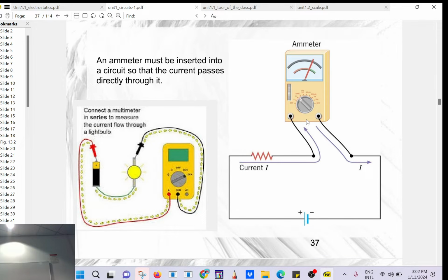So the charges, when they flow, they go through the device, so it's like something is counting back there. What you don't want to do, and you will get in trouble, I would take points off my students when I was teaching lab, is to have your multimeter in amps and measure the voltage with that.